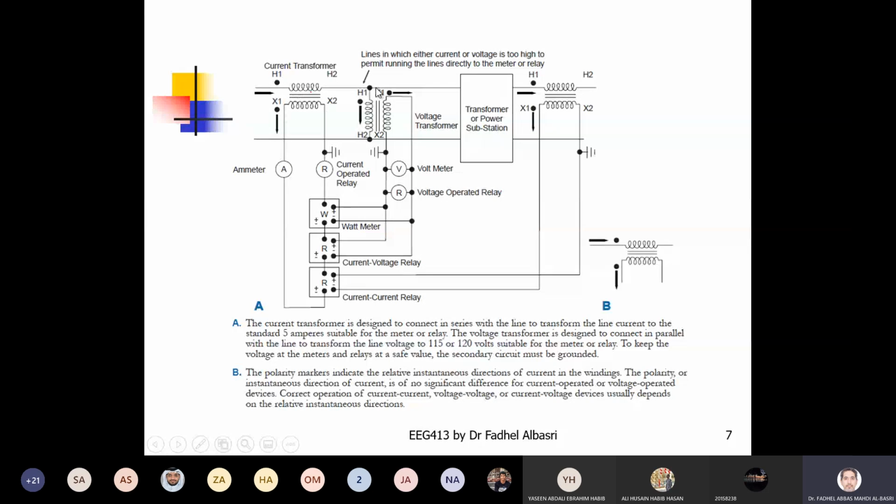So for the primary side of the transformer, I want to measure the primary current that goes to the primary winding of the main transformer. This is the power transformer. Okay, it's not the CT we are talking about. Our CTs are instrument transformers. Their use is not to transfer power from one side to another. Their purpose is either to measure the quantities or monitor that quantity for protection application.